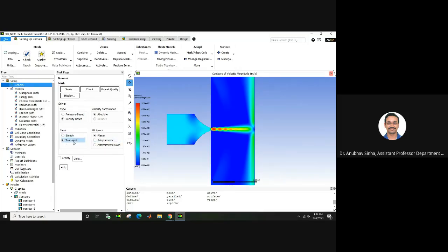You can do steady and transient both. Sometimes steady is a little bit tricky to stabilize, so transient is much better in terms of stability. Generally the cases are steady, but if it is a turbulent case, then transient is what you should do. Try with steady, if it works. Otherwise, you can go to transient. Fine. So mesh, I think you all can scale and check.